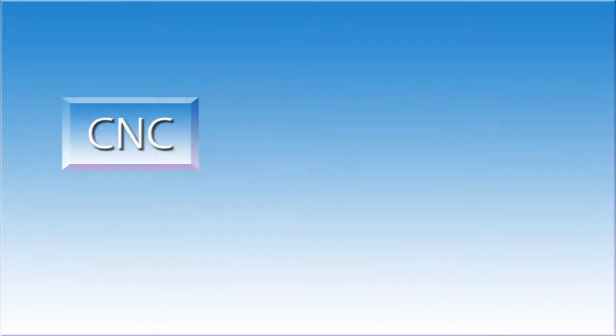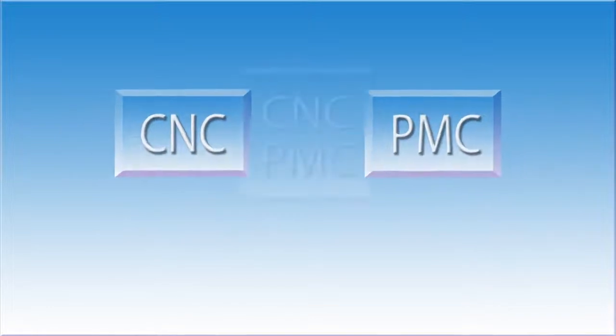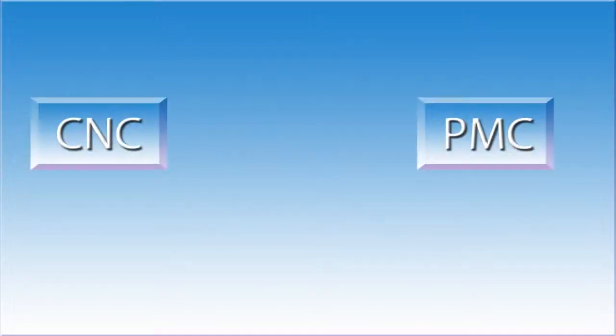Think of the CNC control as two separate devices, the CNC side and the PMC side. They are in fact one computer, but when it comes to troubleshooting, you will find that it is much easier to think of them as two separate items. The PMC and the CNC each have areas of responsibility.